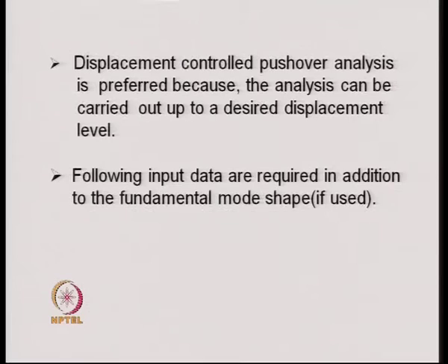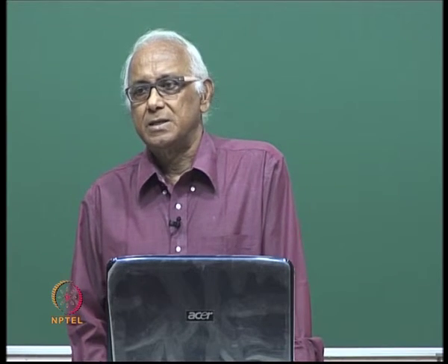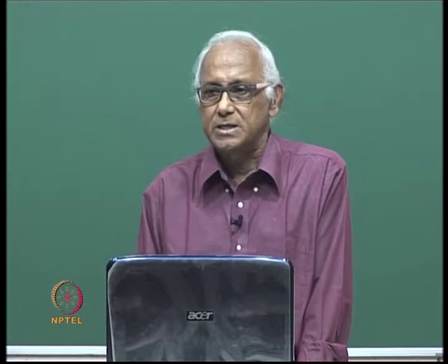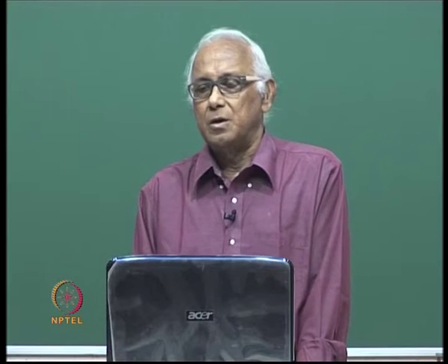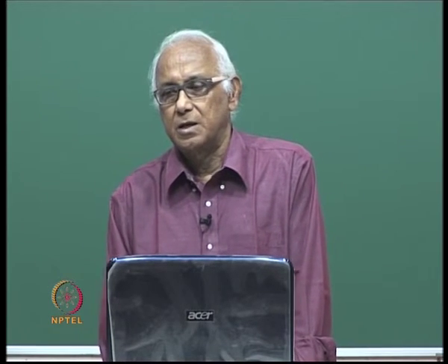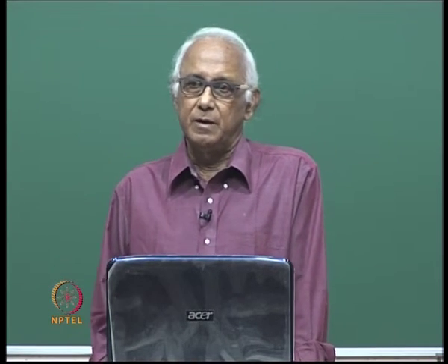The displacement control pushover analysis is preferred in most of the cases because the analysis can be carried out up to a desired displacement level. So, one can stop the pushover analysis at any required displacement stage and say that we are interested to find out the behavior of the structure up to this displacement level.